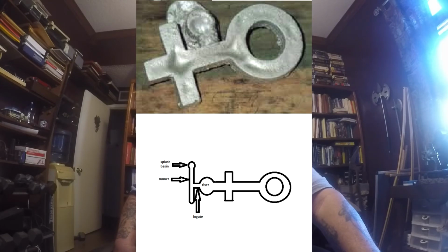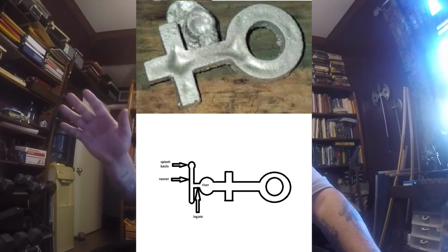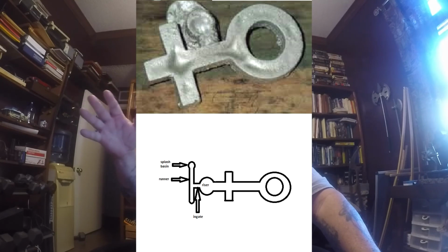The good being on the bottom, and if that was my project, I would have had it to where it was just about 1250. The pouring range on aluminum, as stated in the Navy's manuals, worked very good for me for 20 years. Aluminum, the pouring temperature is 1250 degrees Fahrenheit up to 1400 degrees Fahrenheit, and if you go beyond that, you're going to get what you have illustrated in the photo above.